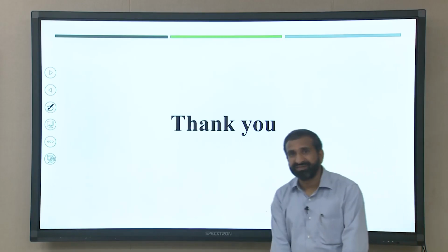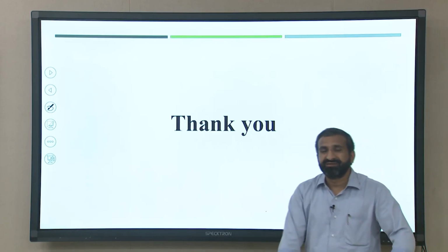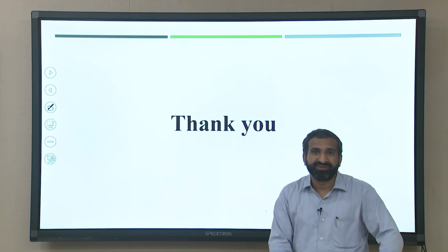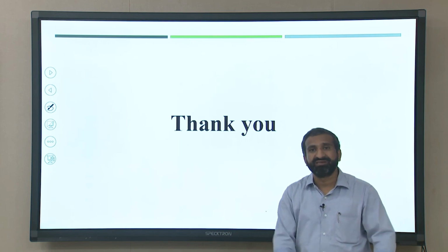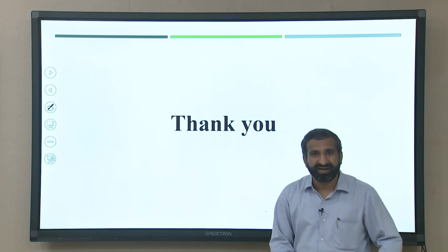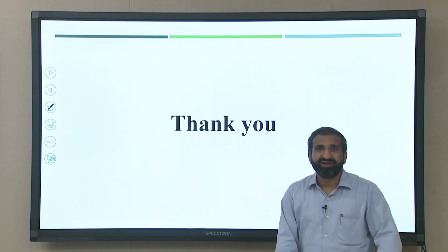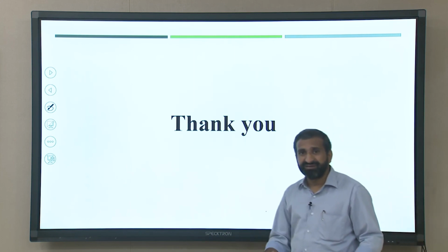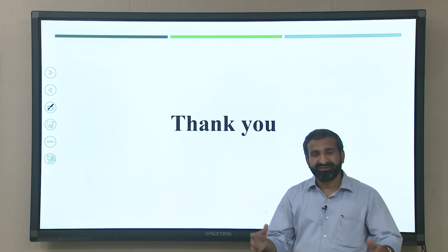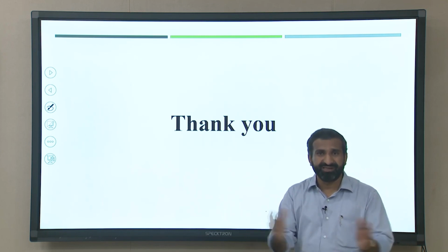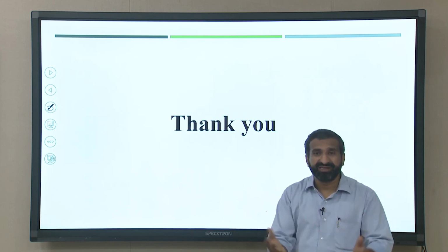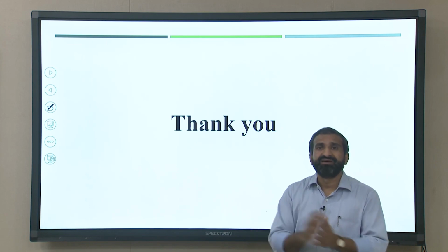So, we will finish this lecture. In this lecture we saw how, in the hauled container system, we can calculate the haul constants A and B, followed by the haul time from the plotted graph, and also from the given data how we can calculate the number of trips per day, and design the time period in a work day. In a work day we can go more than 8 hours also, or we can increase the number of trips. By that we can design.